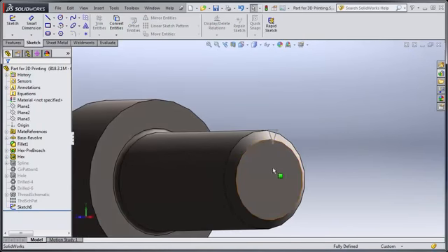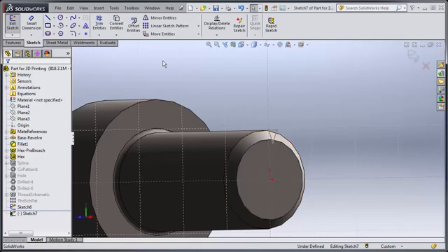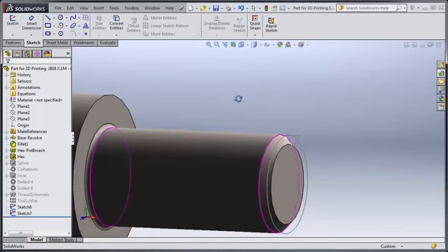Okay, so the next thing I'm going to do is create my path sketch. For this, I'm going to create a helix. To create a helix, first I'm going to create a circle. I've used convert entities to convert my existing circle to ensure that it's the same size. It doesn't actually need to be the same size though. It just makes it easier to see what's going on if it is.